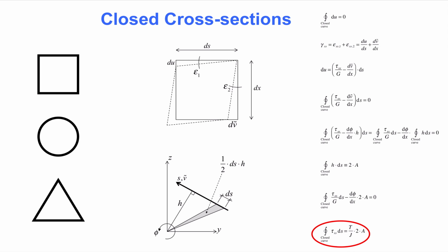When postulating a stress function under these circumstances, the constant value of the stress function around the edge, dictated by the boundary conditions established in the video of Saint Venant torsion, may be different for each of those lines. In other words, if we set the constant value to 0 along the outer edge, then we cannot say that it is 0 also along the inner edge. The boundary condition simply says that the stress function must be constant around all free edges. As a result, a stress function with more than one unknown is needed. In turn, more equations are needed to determine the unknowns.